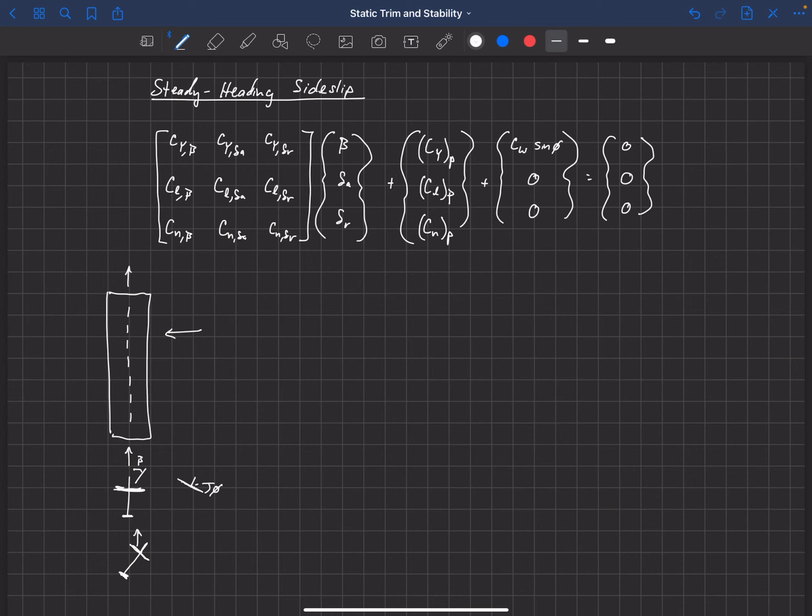And what happens is we've basically gotten rid of beta, but we've changed the orientation of the aircraft relative to its heading. So it's still moving in this direction, but it's oriented with its nose pointed into the wind here. And so what that does is you can make beta really small and therefore phi really small and trim the aircraft with a nearly zero bank angle.